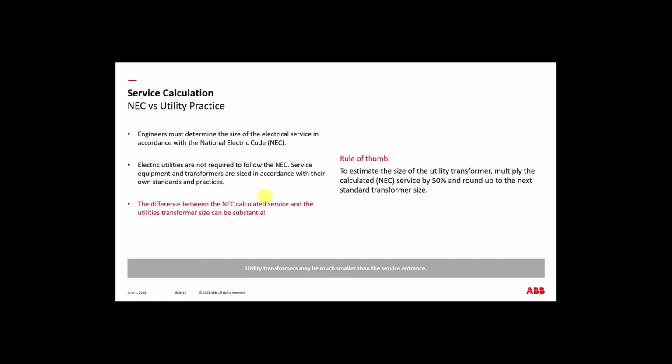That's where they are interested in the largest motor. So usually when you fill out a utility application for a new service, you have to list the big motors you have, because those are the wild cards, because those don't get accounted for in their watts per square foot table.